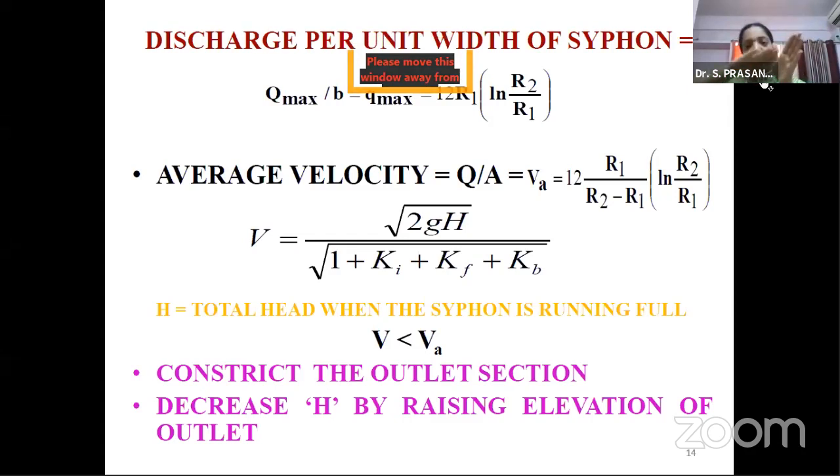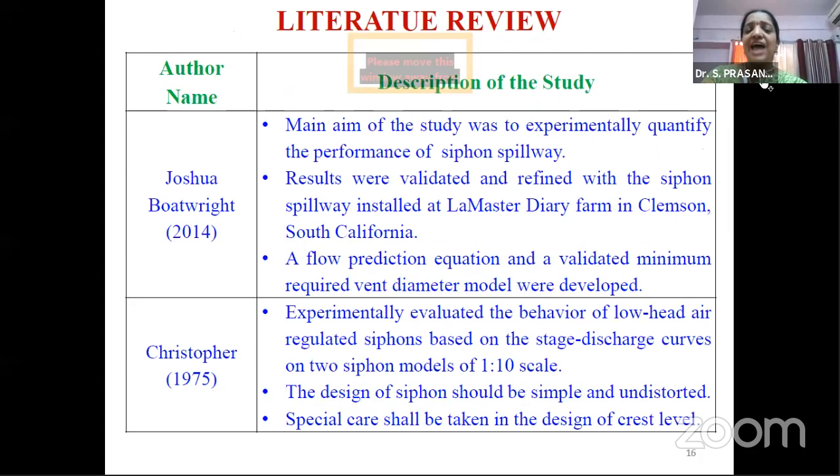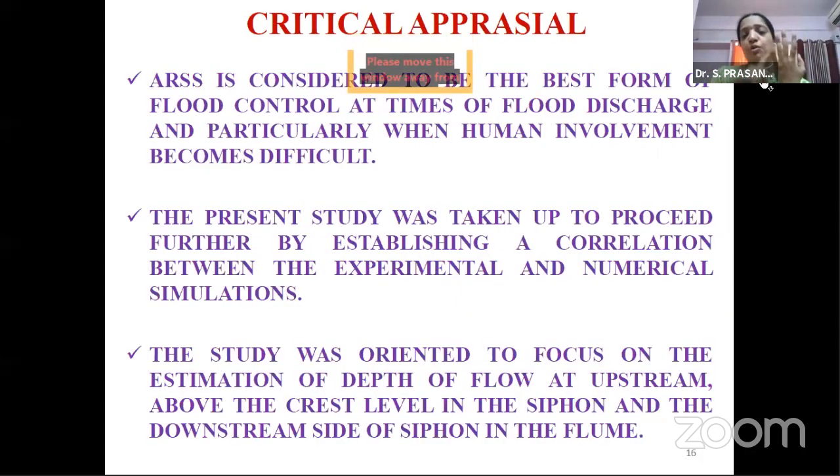Now, coming to K omega, it is a little bit different form of dissipation value that is going to be given. So in that case, as I've shown you the equations, both the equations have the transport, destruction, dissipation, and convection properties. These are the normal turbulence properties which both the equations can solve. So normally everybody, because I have done so many applications, and I have seen the papers also, and the literature also says that K epsilon is the best model.